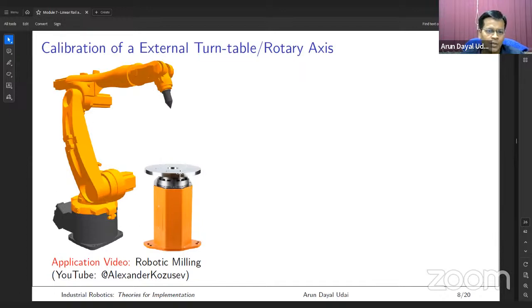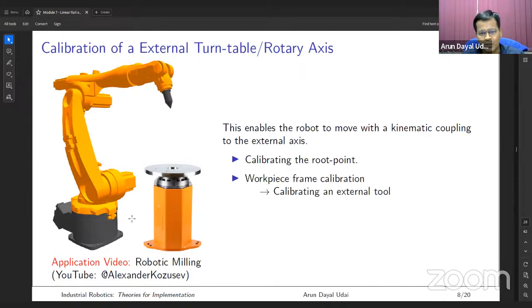You should know which axis it is rotating about with respect to your robot frame. Robot manuals let you do a few touch-ups on these tools and the external turntable, and it finds the error, the calibration matrix, automatically. But it won't tell you what mathematics they have done.